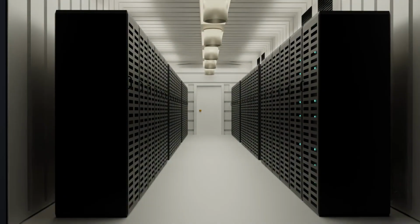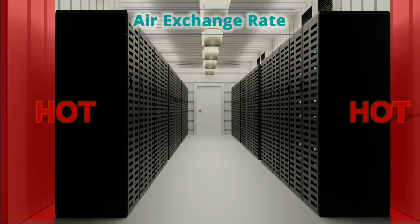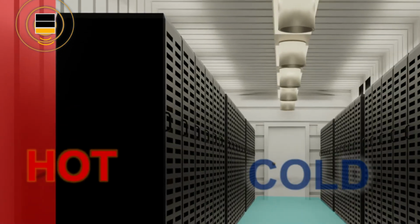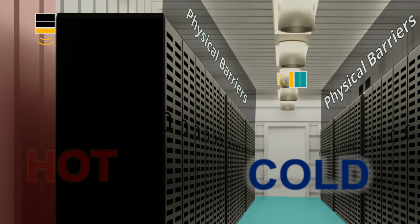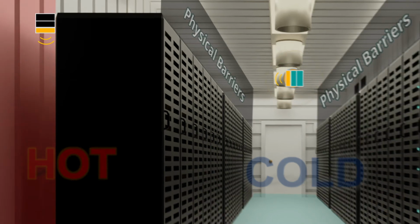The most important information related to air exchange rate are the locations of the hot and cold aisles. Monitoring sensors should only be located in the hot aisle. Reference sensors should only be located in the cold aisle. A physical barrier should separate the hot aisle from any reference sensors mounted near battery racks.